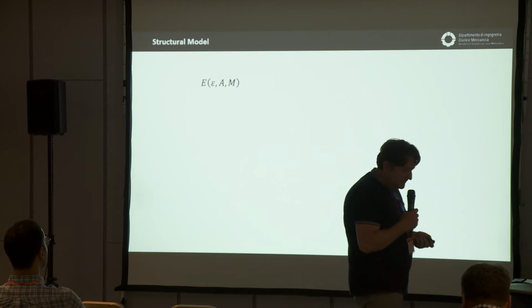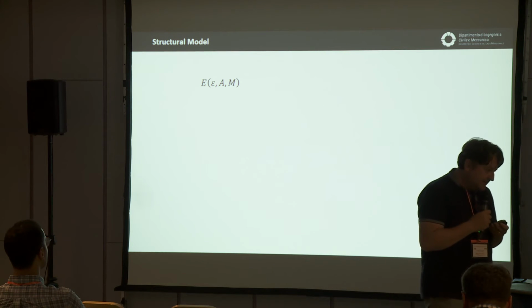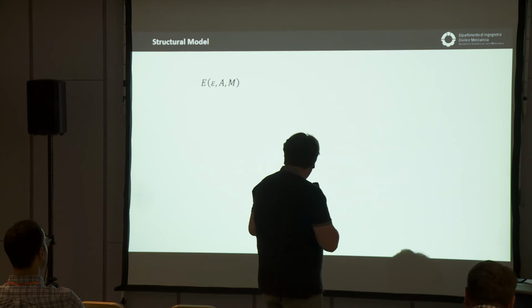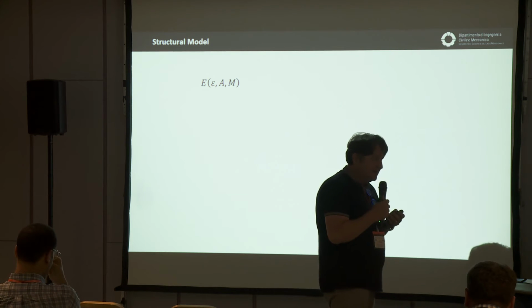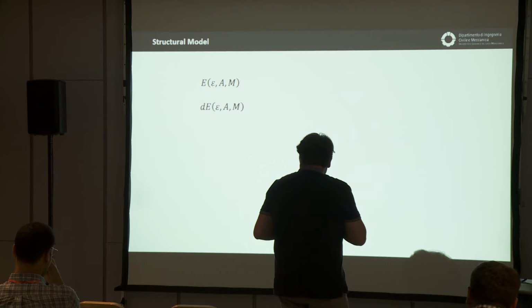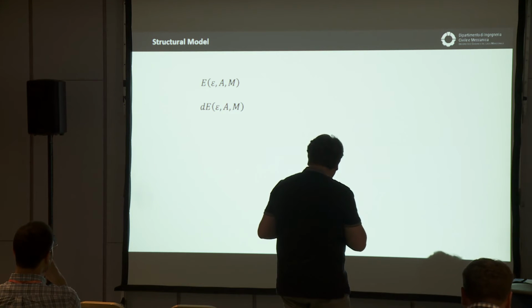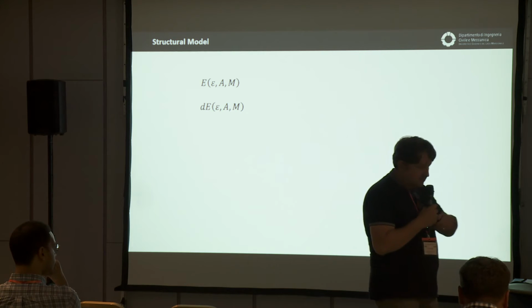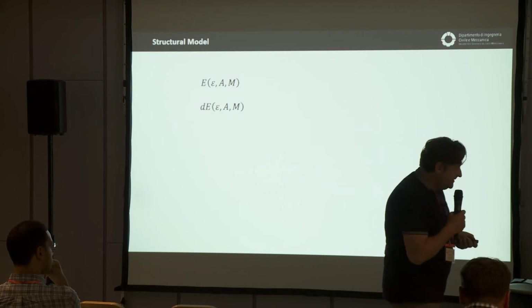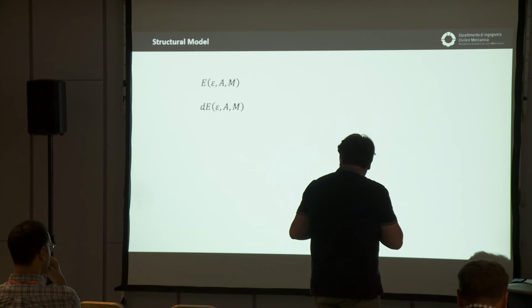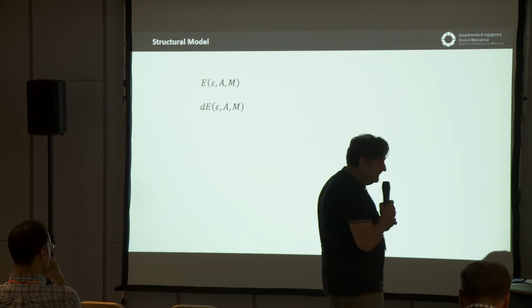Why change the microstructure? How can we take into account the variation of microstructure during the deformation? In a recent work, we postulated the presence of an energy that drives this kind of phenomena, and in differential form it depends on the deformation. Many works in the literature use only this dependency. But we postulated that the austenite volume fraction and martensite volume fraction influence this kind